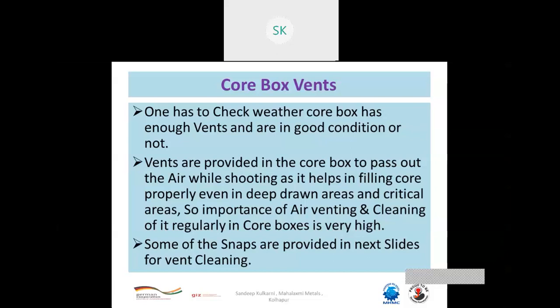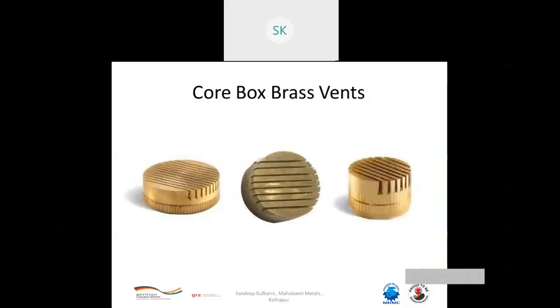You must have good venting, particularly in deep-down areas and critical areas as well. So the importance of air venting, and cleaning it regularly in the core boxes, is very high. Some snaps are provided in a future slide for vent cleaning. So how to do the vent cleaning? These are the pictures of the brass vents which we are talking about.